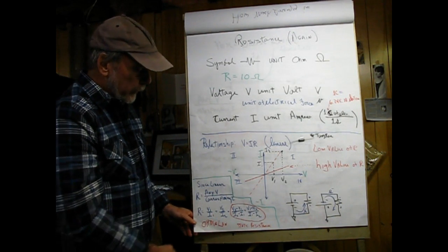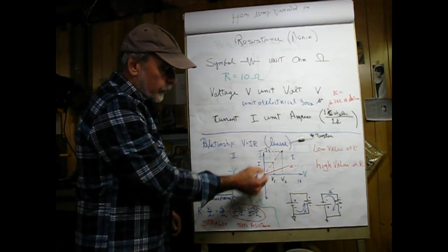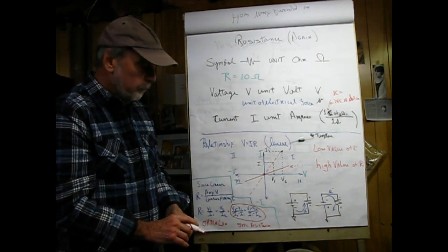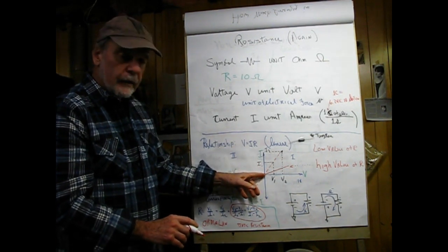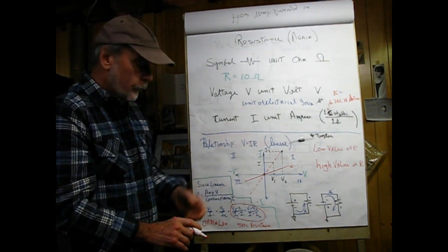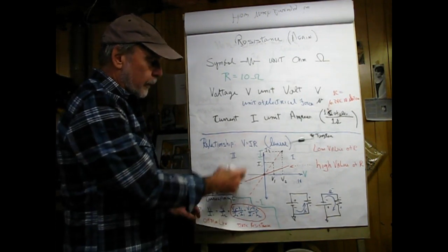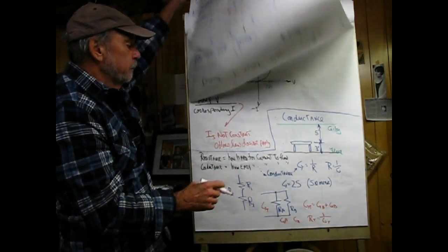So that's important, and the thing to note here is that if the line is steeper, it means that the resistance is lower, and also that all of the lines here have to go through the origin. 0 volts equals 0 current. Now we could decompose this a little bit further, but it wouldn't be productive at this time.